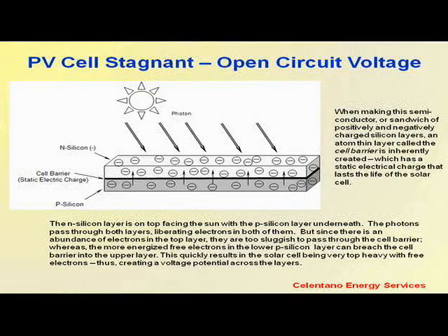Okay, now let's look at how this solar cell works, this sandwich of semiconductors. It is a sandwich of positively and negatively charged silicon layers, with the N layer on the top having a little bit of phosphorus doped into the crystal structure, and the P layer on the bottom having a little bit of boron in that same crystal lattice.